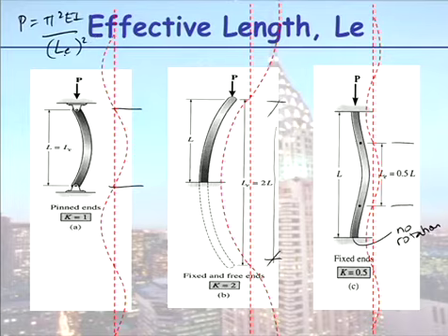Now when this effective length is just equal to L, as compared to when that effective length is equal to 2L, or if it's equal to a half L, can you see, because it's squared, you're squaring the 2 term, so it's a quarter the strength. When you square that half term, it has 4 times the strength.